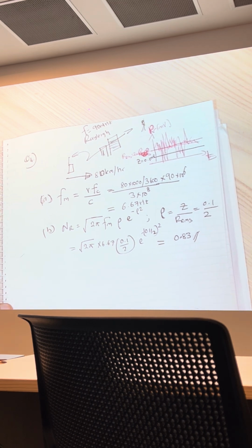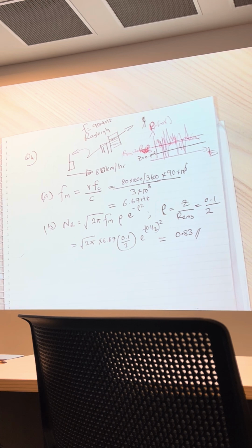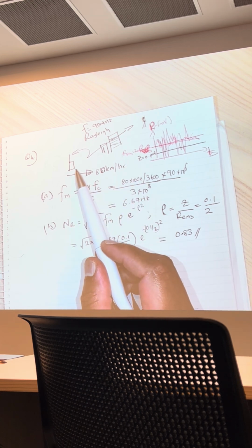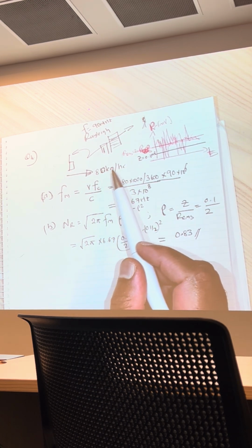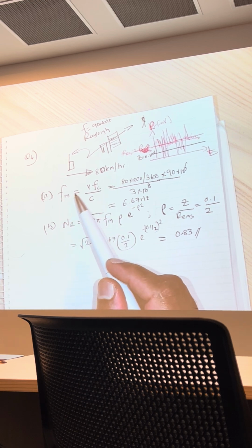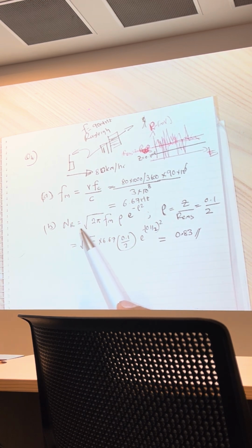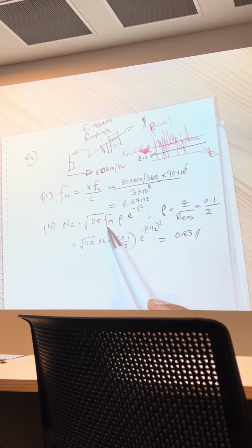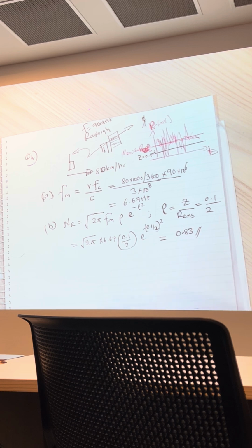So that's the level crossing rate for a Rayleigh channel for this particular scenario. You can see that if the mobile terminal is moving faster, your Doppler will be higher, and therefore the rate of crossing that level will also be higher because it's proportional to Fm, right?